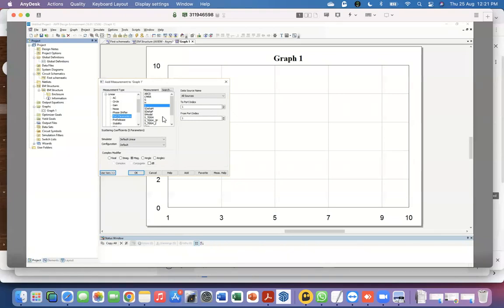So S11, which is what it is set up for right now, means both the incident and the reflected, or the collection port and the source port, are the same. So this actually is what is also called a reflection measurement, because you're sending signal from the same port and then looking at what is coming back, and this plots the ratio of the voltages for the signals.